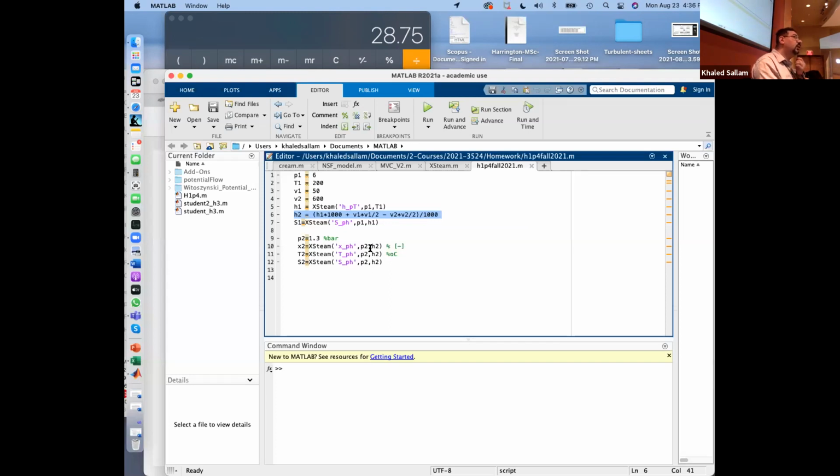And that's actually the homework this week. In the homework this week, we'll see a power plant, and I'm asking you to calculate things in BTU per pound mass. And I think I did say last week, and if I didn't, let me say it again: never use pound mass in your calculation. It's not the right unit to use.